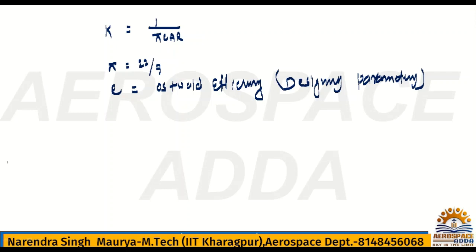Means this E value, Oswald efficiency, will depend on what type of wing there is: rectangular wing, swept wing, swept forward, swept backward, or elliptical wing. But that value will be given to you. Don't mug up this value, because you cannot, since many different designs of wings are available. So for how many wings will you remember the constant? Don't remember, they will give. But one thing you need to remember: E is equal to 1 for an elliptical wing. This is the unique elliptical wing. Okay, this you need to remember.